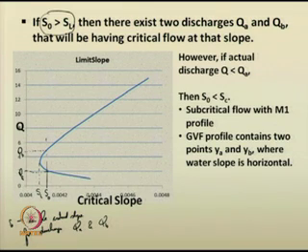So, the bed slope is almost a critical slope. Similarly, just above 4, between 4 and 5, here for QB, S0 is also acting as a critical slope. Like that you can easily observe them. So, how can you observe the transitional profiles in such situations? It depends on what your actual discharge Q is. Say if your actual discharge Q is less than QA, even though your bed slope is S0,